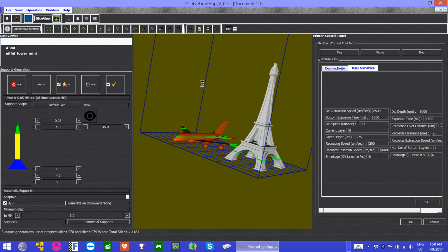So we have a UV light holder in the 3D printer, it will be projected on the layer, and we will be projecting a slice at a time, and after creating the layer we cure it by UV light.